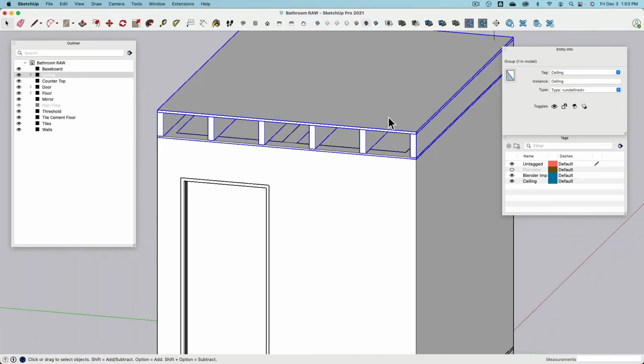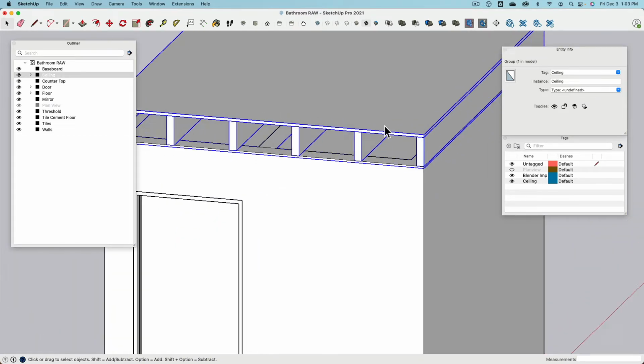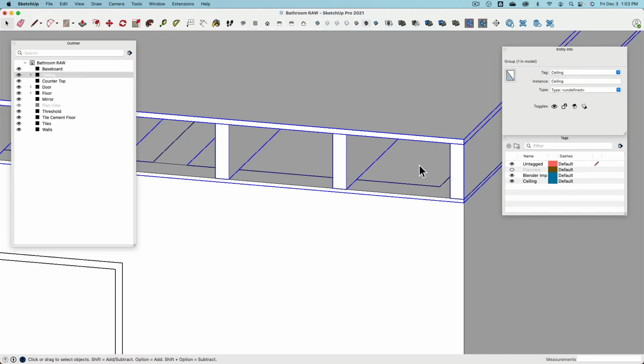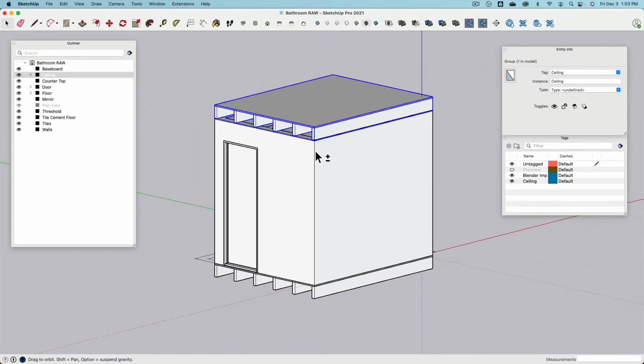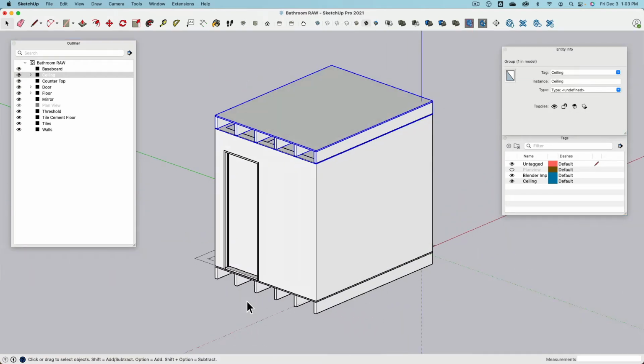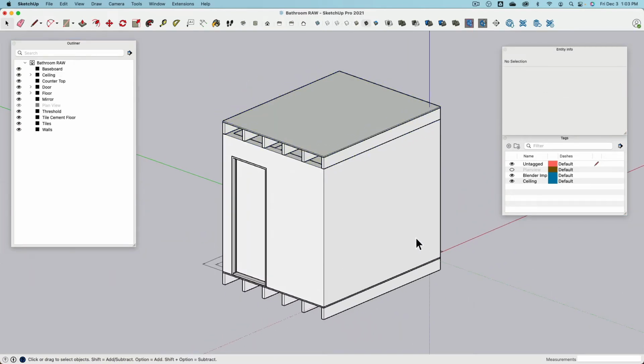On top of the joists is the subfloor again for the second floor. And then under the joists, there is the drywall, which would be connected to the joists, and from the inside we would mud everything. Okay, very good. So pretty simple. And this is not too complex or too detailed. It's still a little bit simplified, but I think you can see that this model is visually very easy to work with. And when we create section drawings, we really have accurate dimensions or geometry we can sample dimensions from.